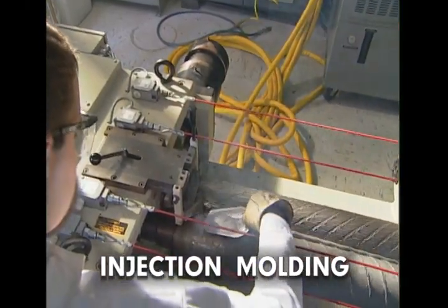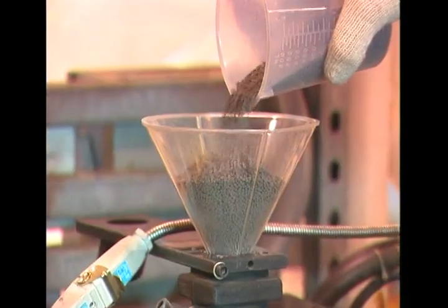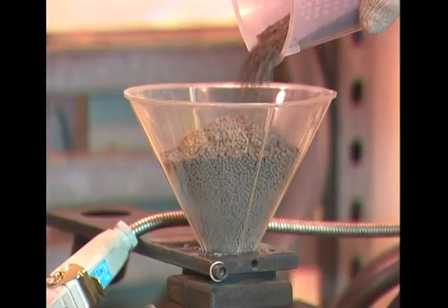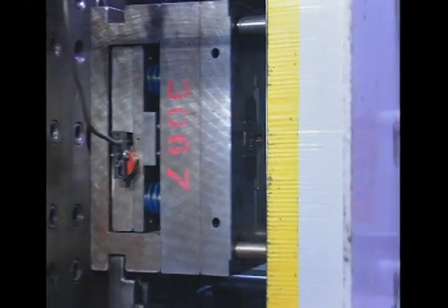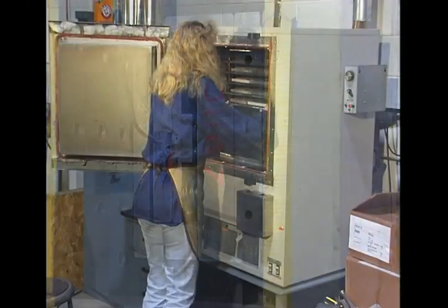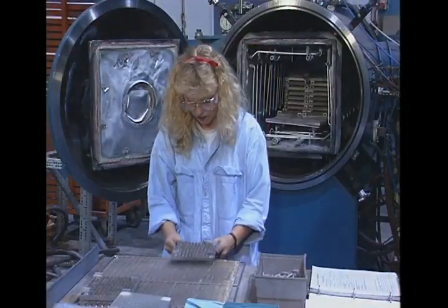Injection molding involves mixing the powder with a thermoplastic binder and granulating it to produce the feedstock. The feedstock is heated and then injected into a mold to produce the desired part. Once the part hardens, it is debinderized and then sintered.